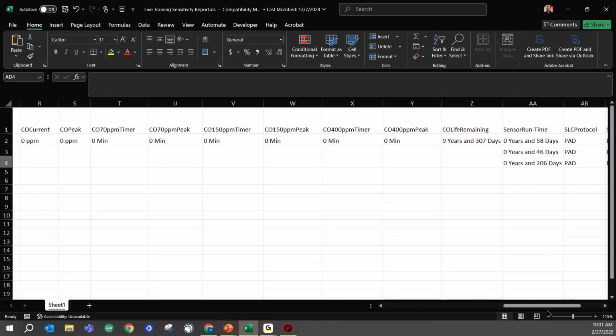Another thing I do want to throw out there, because it seems to be a little bit of an urban legend that I still hear in dark corners of this industry, please keep in mind CO is not heavier than air. It will mix with the atmosphere. That's why we can put CO detectors at the ceiling.